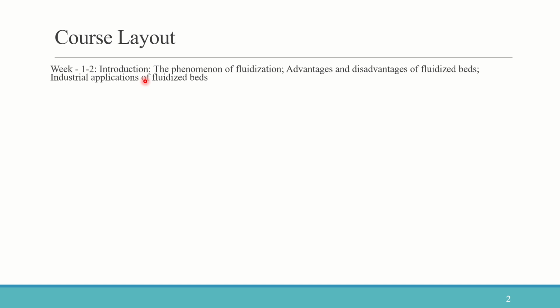Why do we need to go with such high velocities when we already know that if we use a fluidized bed, the pumping cost will increase? Why do we have to go with fluidized beds? Because the contact between solids and the fluid is enhanced in fluidized beds. So if we want higher contact between the fluid and the particles, we can go with fluidized beds. In those cases, the mass transfer and heat transfer coefficients are increased.